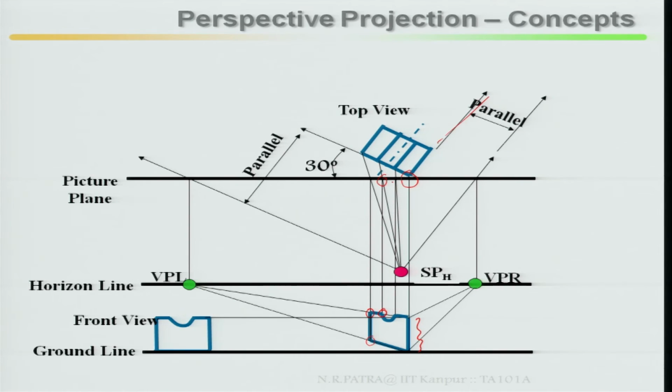If you look at your top view, this is a hole, this is a dotted line, this is your center line. So taking it as a diameter, half of it the radius, find the center line and draw the arc. Then look at the right edge, which has been located from here to here, and mark it.